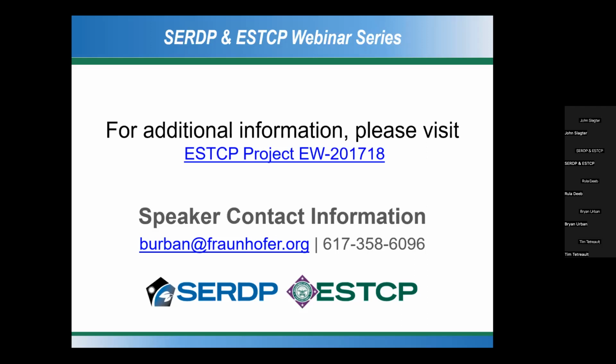Yeah, so that's another good question, because obviously you can do a whole lot and provide a lot of flexibility and savings, but this kind of system might be overkill if you're just doing a small retrofit in a conference room or part of a building. If you're investing in a whole lighting control platform, you want to make sure you're doing enough facilities to make it cost effective and worthwhile. On the control side, there's a couple things to consider. You get the most savings out of daylight harvesting, obviously, if you have enough windows or enough available daylight.